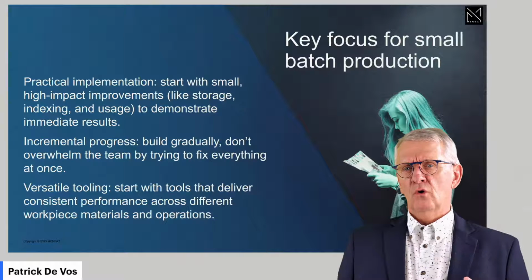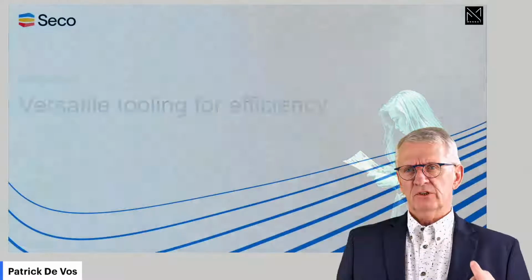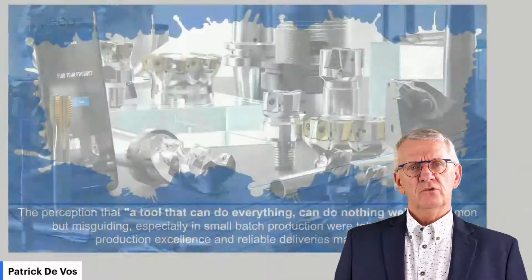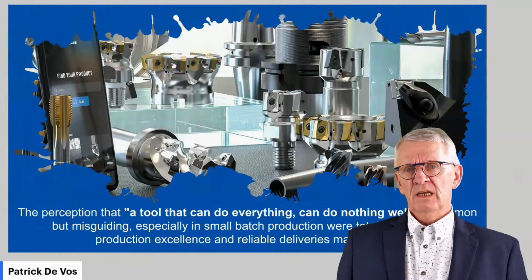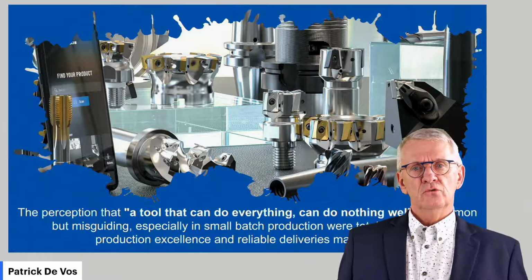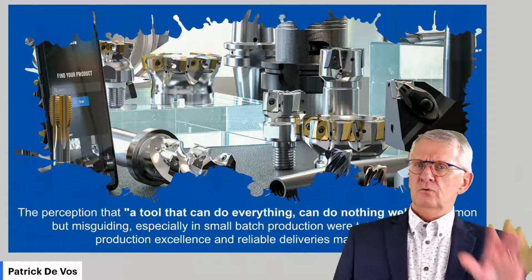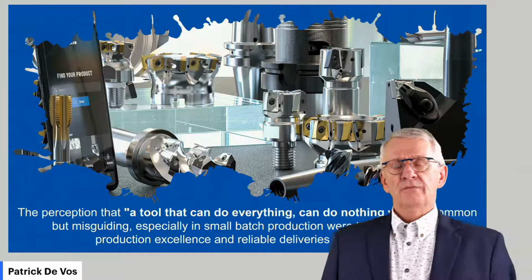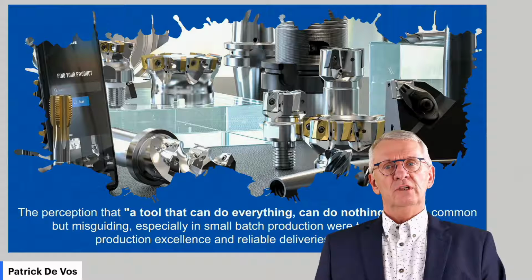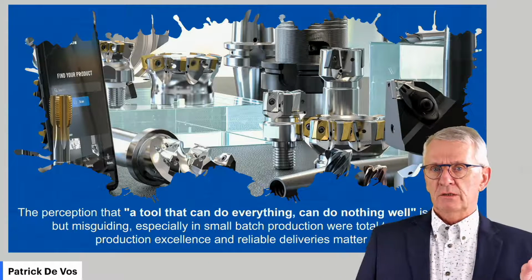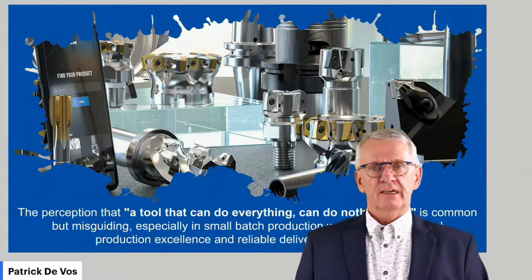And if it's small batch production, already here we should pay attention to versatile tooling, and a few words on versatile tooling. Because if we look at tool selection, and I use the word versatile tooling or universal tooling, a lot of technical people say, oh, no. A versatile tool is a tool that can do everything but nothing well. So that's not for me. I want good working tools.